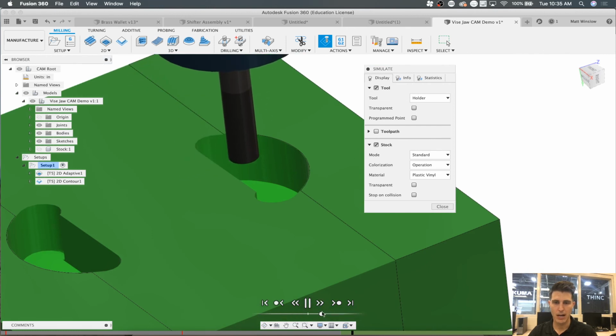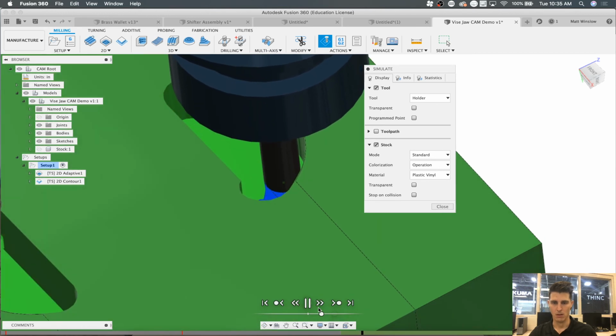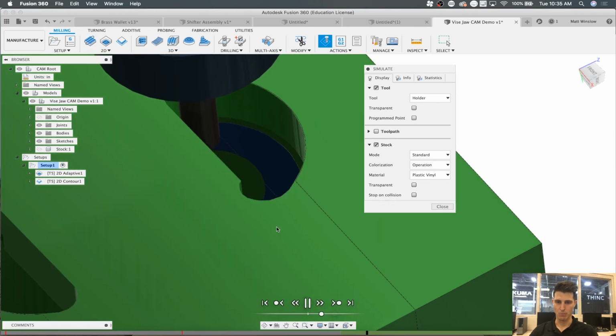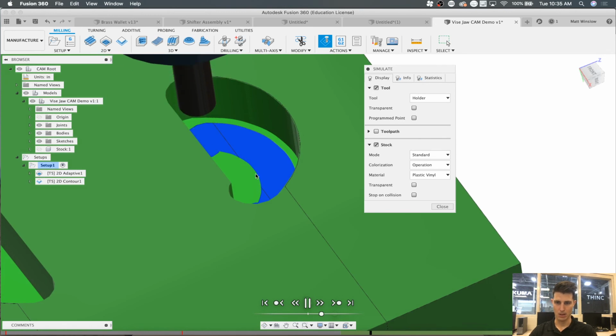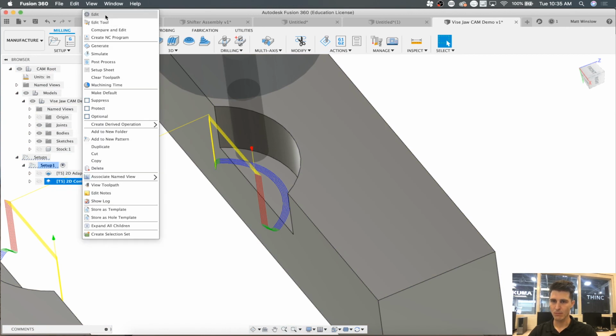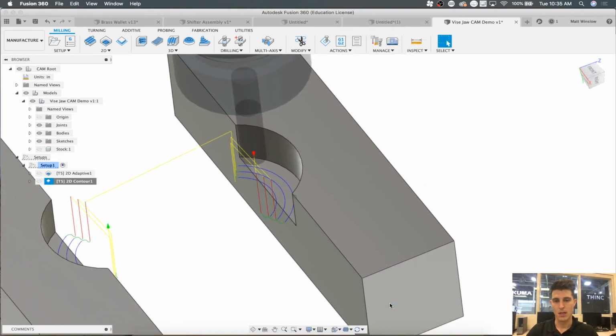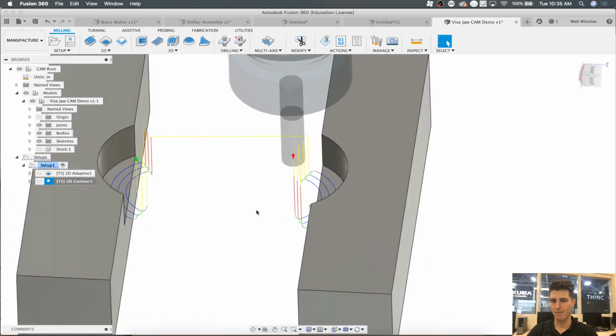So scale this back, run a little slow, let's see what I'm working with. See how we're just barely missing that? So I'm going to go ahead and change that a little bit. My step over for my finishing doesn't need to be that light. I mean, I could do 3 passes of 125 thou, and that would work. Yep, so now I'm covering everything.